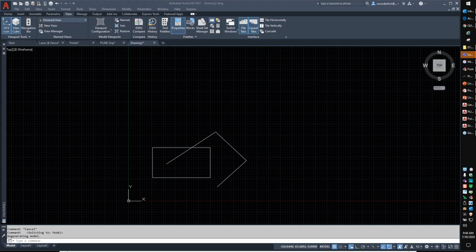All right, if you are seeing the command line instead of the dialog box for commands like tcount, you need to put in CMDDIA, and that needs to be set to 1. If CMDDIA is set to 0, anything that should pop up a dialog box is only going to appear in the command line.